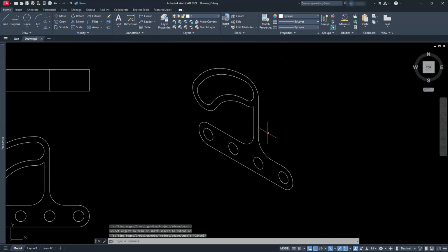Okay, so from this point we're ready to start copying things, right? So we know the width of this is going to be 30. Let me go ahead and switch to an isometric right. Choose copy. And I'm going to select these shapes here.